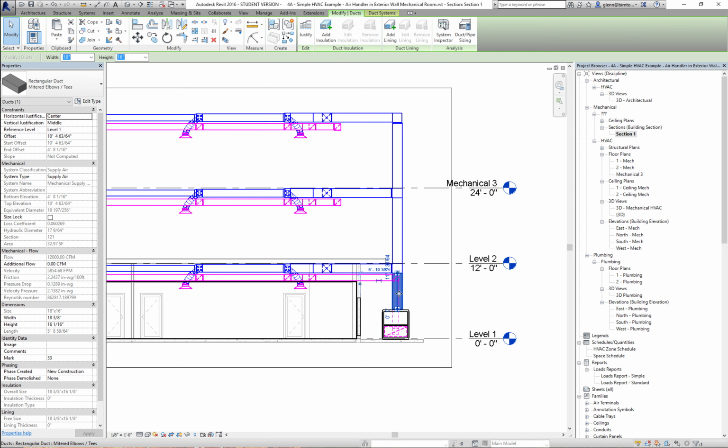Yeah. Ultimately, if the pressure were all even, it should balance itself out. But the further you get away, all our perfect assumptions somehow don't work out. Even though theoretically it's all balanced so that the end point gets the same delivery as the first part, it isn't realistic. So we typically divide it into subsystems. Even in a really tall building, a single air handler holding 2 or 3 floors is probably fine. If there were 7 or 8 floors, you'd probably think about several different air handlers, splitting the load up a little bit.